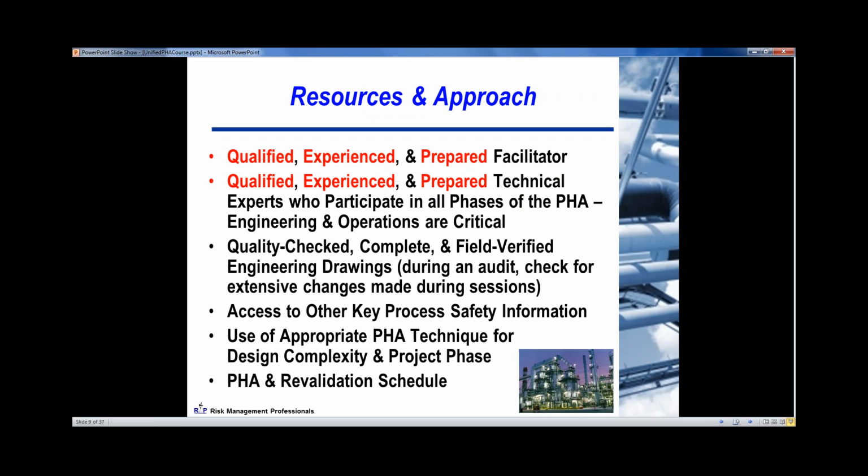The third item, quality checked, complete, and field verified engineering drawings. It may seem very obvious to most of you that you want to have correct information so that you have good information to go into your process, and then you've got good information coming out. Unfortunately, that's not always the case. Invariably, there's always little mistakes in piping and instrumentation diagrams and other engineering information. Doing a quality check and field verification to minimize those, so the team can really focus on their job rather than on correcting something that could have been done beforehand, is super important.